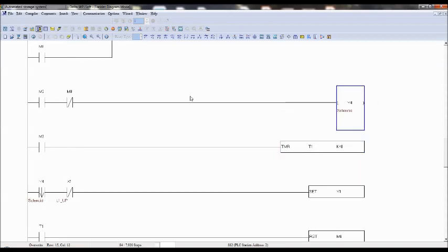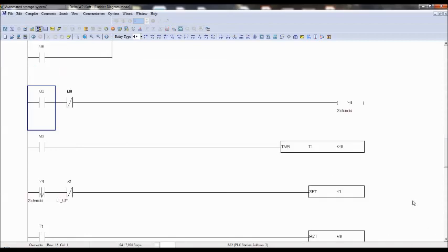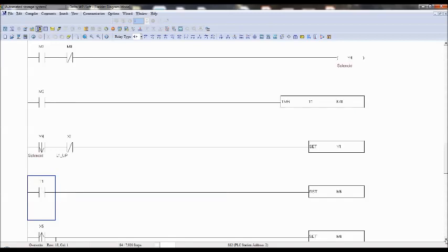So whenever it has reached the rightmost position, again we are going to switch on M3 with the help of M6 dummy variable or M6 internal memory. So again, whenever M3 is on, solenoid will extend. Again, solenoid will be off. So whenever solenoid is on and off again, I am using the falling edge signal here. Again, it gives a signal for M6.